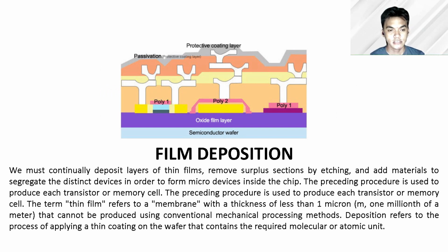So the next step in manufacturing semiconductor is etching. After the photolithography of the circuit diagram is completed on the wafer, an etching process is used to remove any excess oxide film, and only the semiconductor circuit diagram is left. To do this, liquid, gas, or plasma is used to remove the unselected parts.